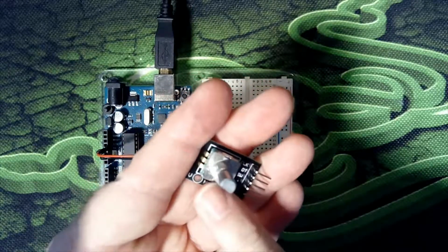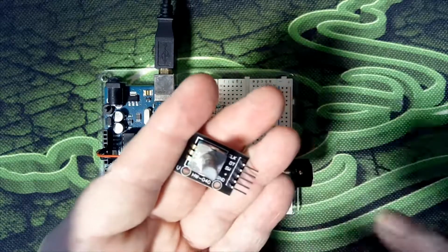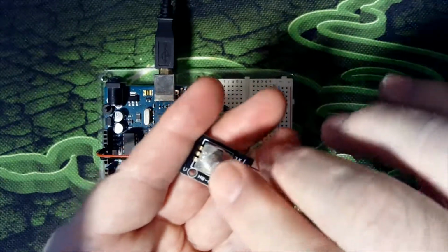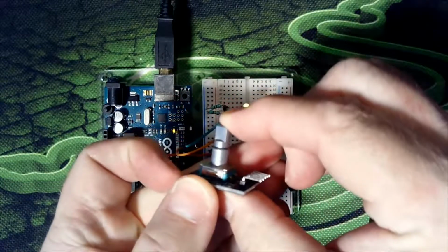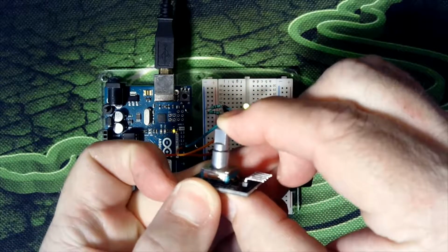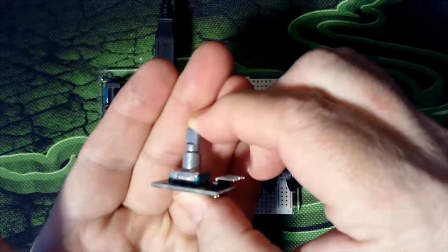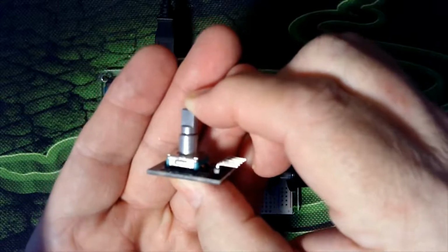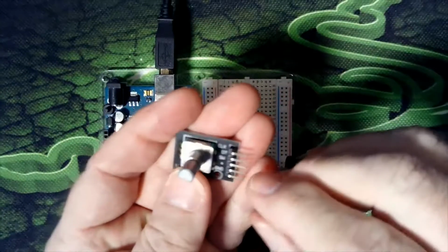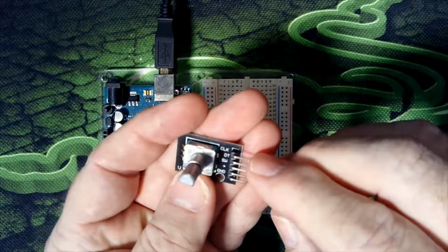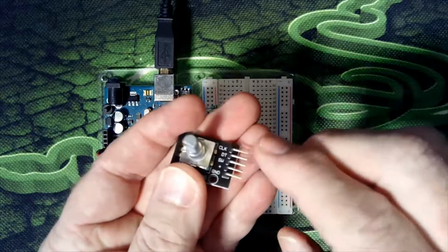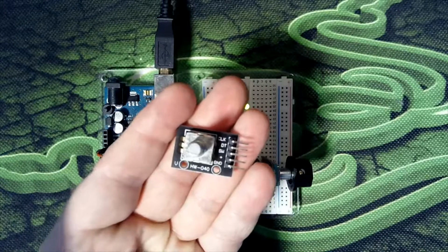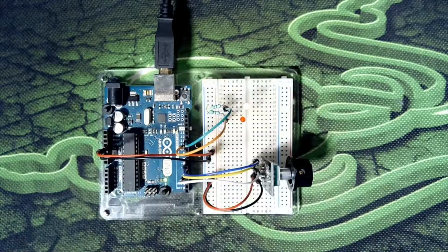There's nothing electrical, there are no optical sensors in here, and I'll talk about that with the different styles of encoders. But what we have in here is a switch, because the center you can actually barely push down, and you might see that pushing, ever so slight. And when it does, it closes that contact to the switch. And then the clock and the DT are your A and B pins. So those are your 2 pins where we're getting the encoder pulses. So that's what we're using today, and I just have it already attached to the board.